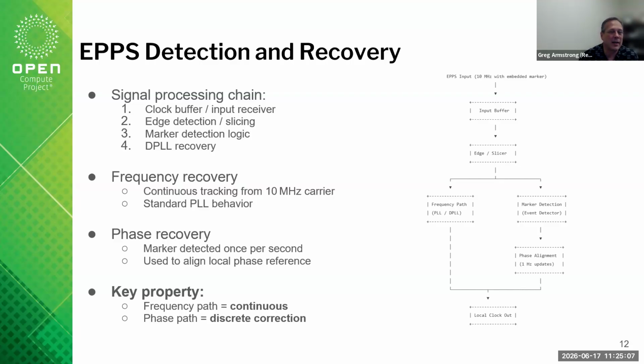But fundamentally, a lot of the logic that's used, even with traditional silicon that's doing any sort of timing, either clock generation or jitter attenuation or buffers, things like that, the fundamentals are still there, right? You're going to have some sort of input buffer that translates that signal coming in, whatever it is, CMOS, HCSL, whatever it is, it's going to come into the input buffer.